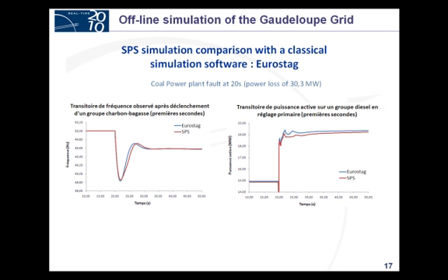The main difficulty to do that is that you have a lot of parameters from the generator, and somebody knows that perhaps, Eurostag and simple system don't use the same, for example, per unit system for the synchronous machine. So the main difficulty was to transfer the parameters from Eurostag to simple system. So you have a lot of work behind this before obtaining this kind of results. But you can have the same results in simple system as in Eurostag.